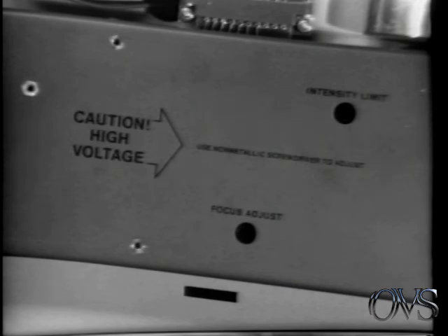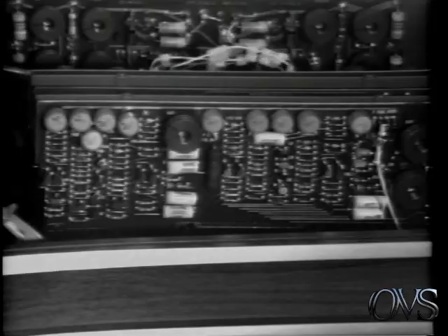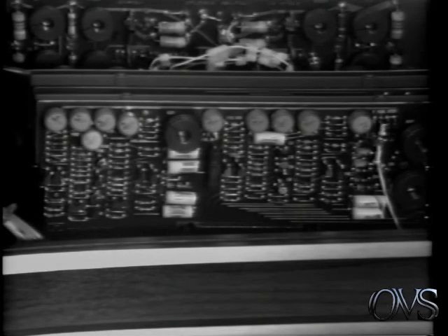First, locate the corner of the screen that has the best appearing spot. Leaving the focus and astigmatism control centered, adjust the focus limit adjust and astigmatism balance adjust for the best focused and roundest spot in that corner. Next, locate a spot halfway toward center screen along the X-axis and adjust X-axis astigmatism adjust number 1 and X-axis focus adjustment number 1 for the best spot at that location.